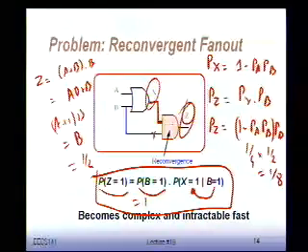High-level simulation can be done real quick. Feed the patterns through it, figure out transition probabilities at every node, multiply that with the capacitance, and we have our dynamic power. Okay? And if you want to do power analysis in a project and you want to do power minimization, doing some style of analysis like this is probably going to be the better choice. Okay?